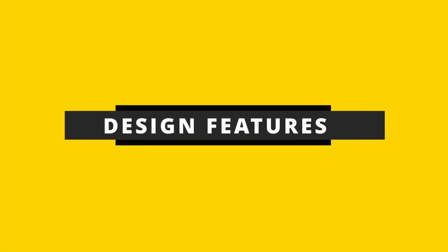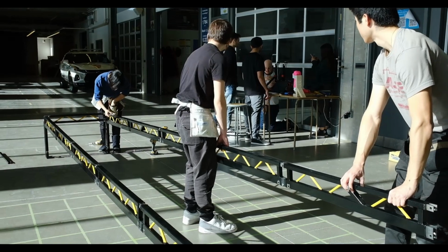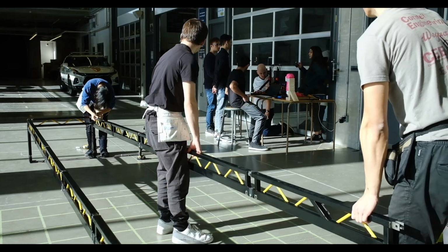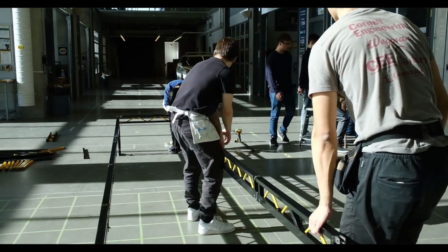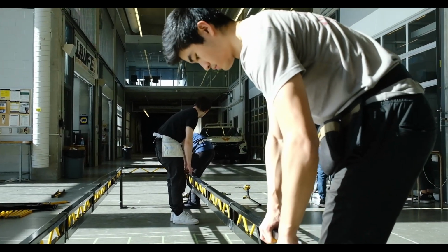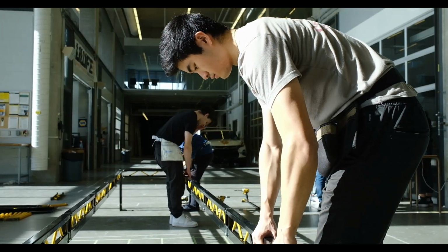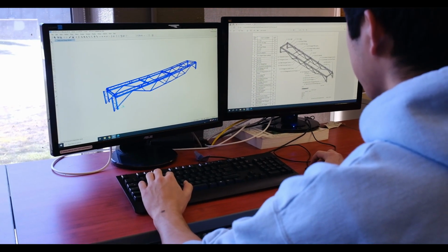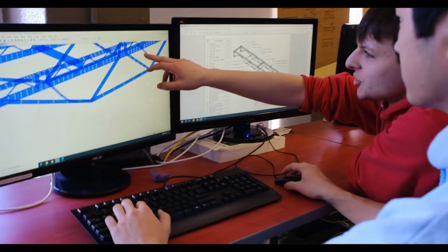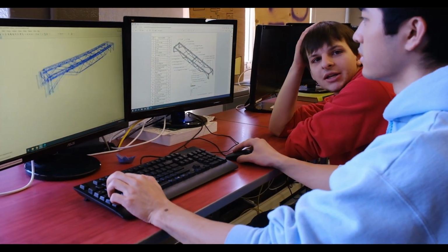The most prominent features of this bridge lie in the design aspect. The bridge uses sturdy truss members capable of supporting themselves as a top chord for ease of constructability. A second under truss maximizes use of the available depth in the bridge envelope. The design of the top chord in terms of increasing moment of inertia is, first of all, identifying what we want to improve under the envelope restriction that doesn't allow an arc. We decided to rotate the stringer, resulting in a wider horizontal section, which increases the moment of inertia during lateral loading. Moreover, the combination of knee braces and outrigger truss legs shorten the effective span of the bridge, which reduces deflection for the entire structure.